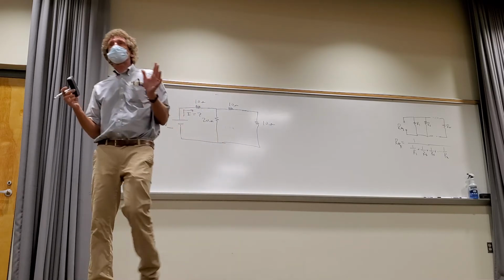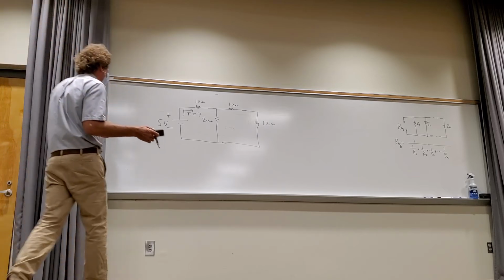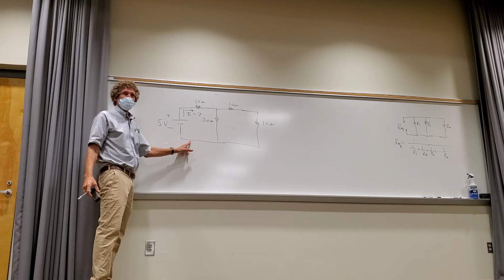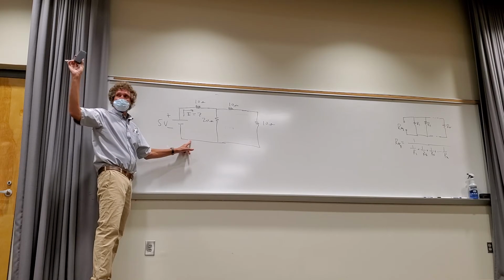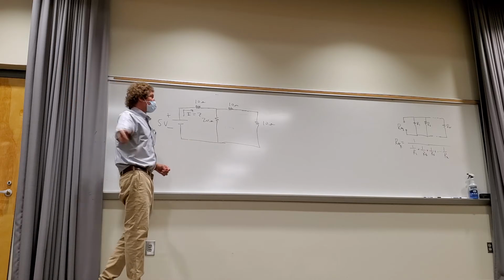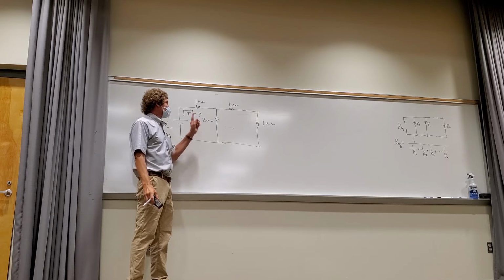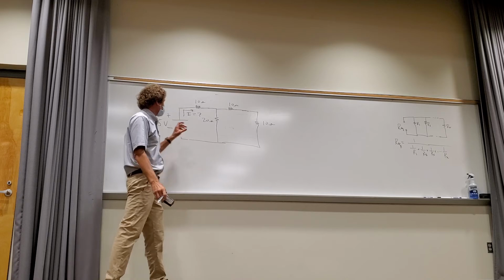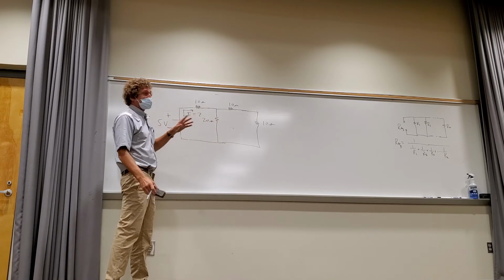Anybody in the back? Anybody see something we could do to simplify this? If we want I, what do we really want? We want the equivalent resistance, don't we? Isn't that right? How many see that? How do we get it? Do you use parallel? The 10 and the 20 parallel? Well, are you talking about these two? They're not in parallel, are they? The voltage here is not across these two. As a matter of fact, they're anything but parallel.